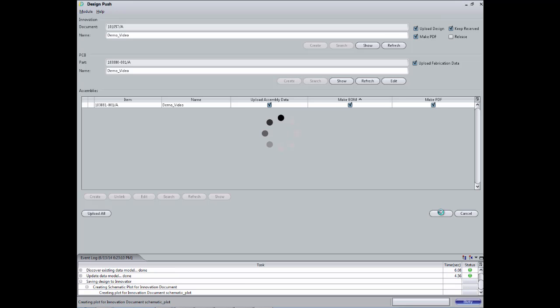Based on company needs, the release checkbox could, for example, just release the design container, release all created elements, or start a release process within the PLM system. Now the module will create the structure in the product lifecycle management system. Vice versa, metadata is transferred into the design. We will show that later on. In addition, the module will produce PDF files, PCB fabrication and assembly data.